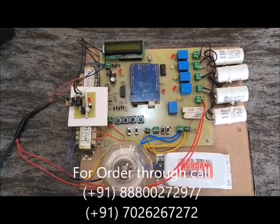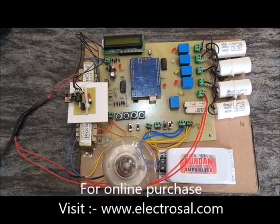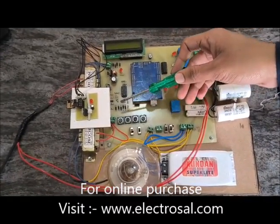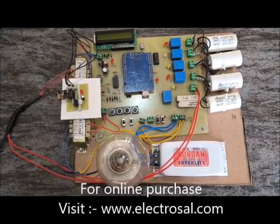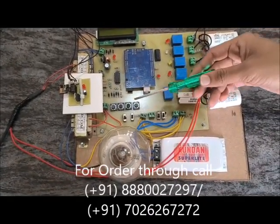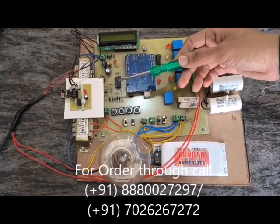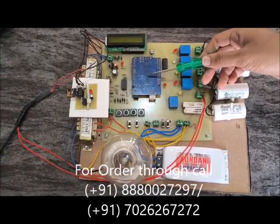In this project we are using an Arduino microcontroller which acts as the brain of the system. To detect voltage and current zero crossing, we have used two zero crossing detector circuits. These are built using operational amplifiers in comparator mode. One zero crossing detector is connected to the voltage signal and the other is connected to the current signal. The outputs of these circuits are fed to the interrupt pins of the Arduino.